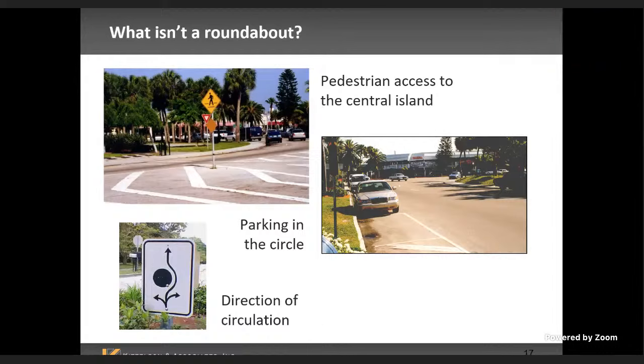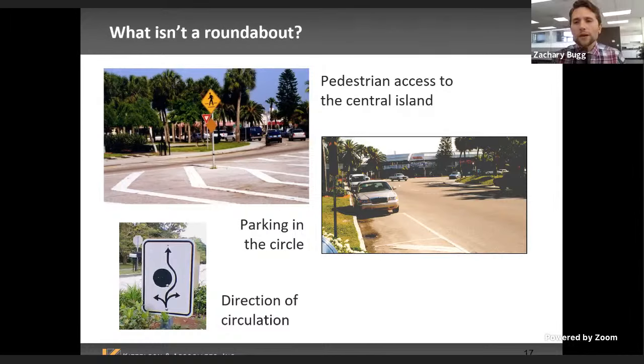It would impede flow, basically. Yep, it would impede flow. Now, there are crosswalks at roundabouts on each individual leg, so that impedes flow too. What is it about having them go to the central island that might be an issue? So I think the biggest issue here is, let's just check the chat. Yeah, so potential danger to pedestrians, a safety issue.